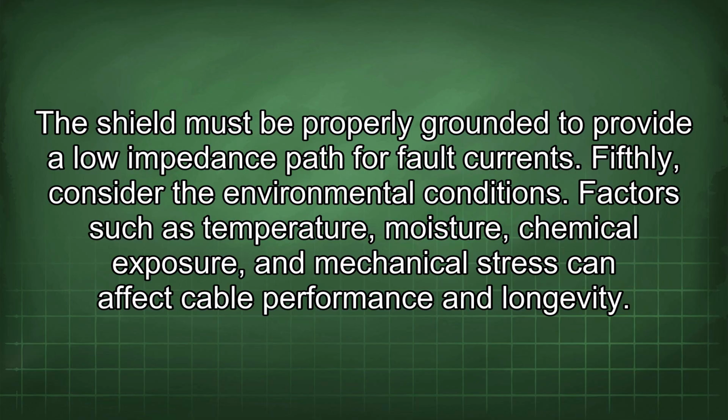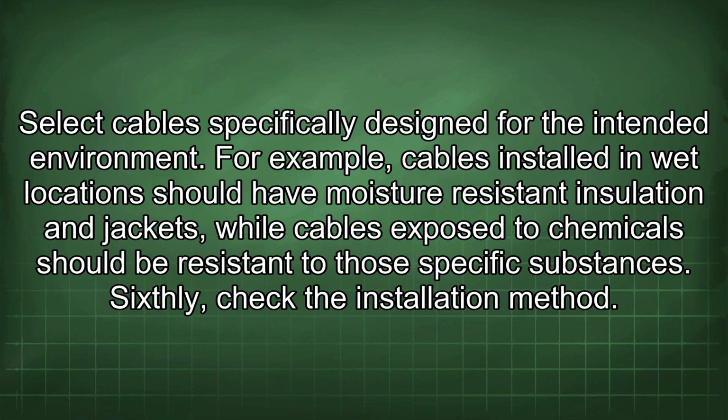Fifthly, consider the environmental conditions. Factors such as temperature, moisture, chemical exposure, and mechanical stress can affect cable performance and longevity. Select cables specifically designed for the intended environment. For example, cables installed in wet locations should have moisture-resistant insulation and jackets, while cables exposed to chemicals should be resistant to those specific substances.